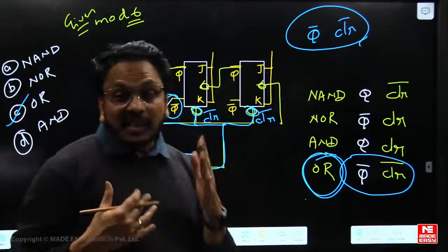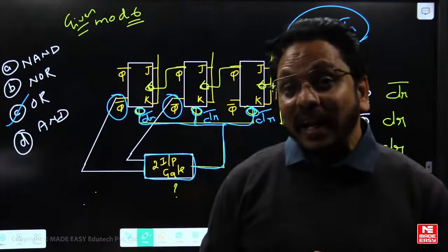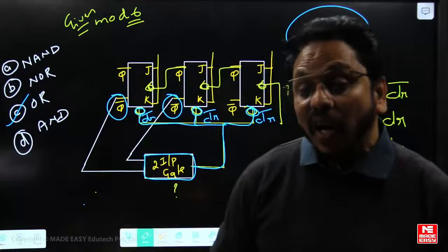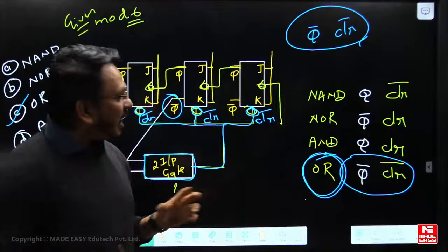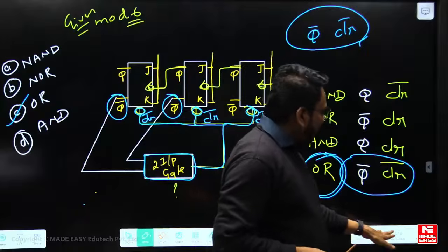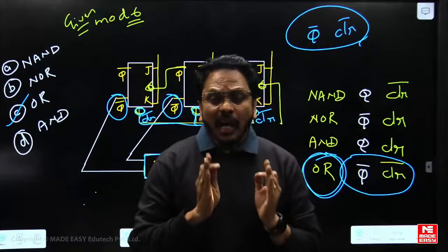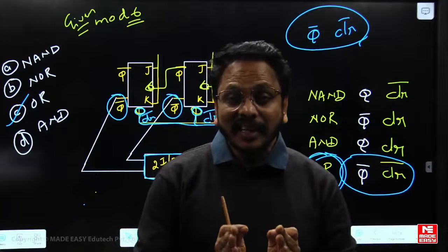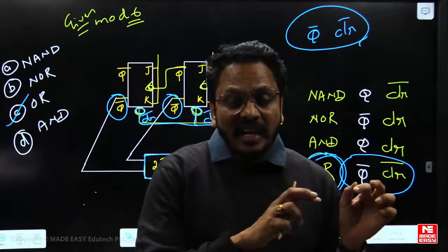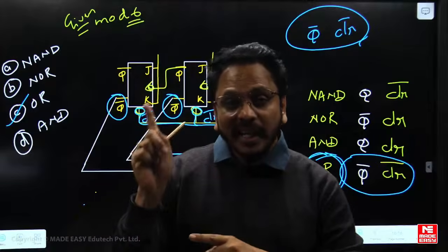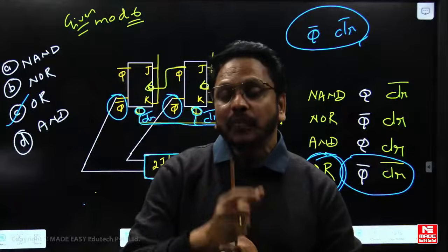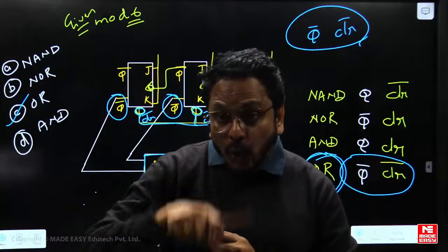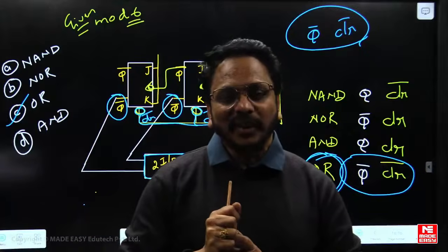Now, about asynchronous counters like this, in the same manner for synchronous counters, they will ask the mod value. Then how do we handle that? Let me conclude this one. The short technique is, first, whether it is an up counter or down counter can be decided this way. Negative triggering: if connected from Q, it is the up counter. If connected from Q bar, it is the down counter.